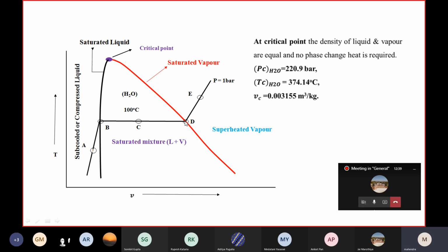After the saturated vapor, still we are supplying the heat. It is completely vapor. What is happening now? Only the vapor temperature is further increasing. This we can call superheated vapor. This is the superheated region and this is the latent heat region. This is the subcooled region. Okay, and if you observe over here, when you are increasing the pressure, suppose this is 1 atmospheric pressure we have taken.